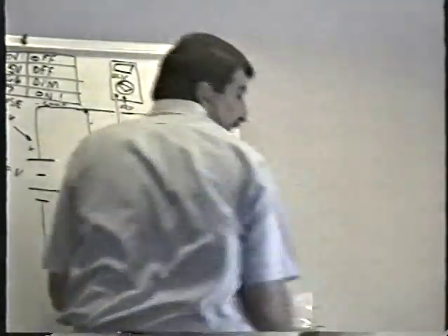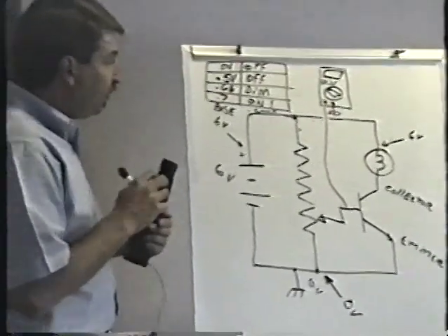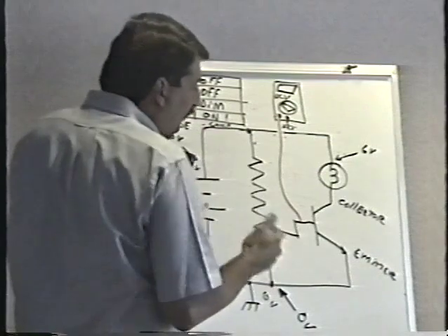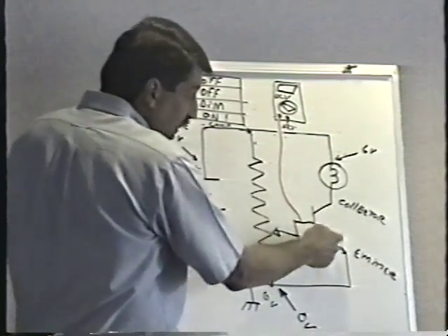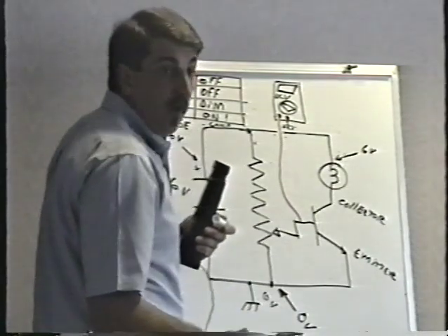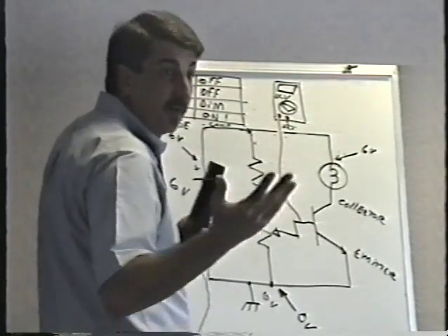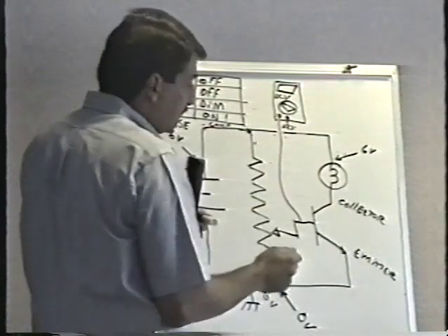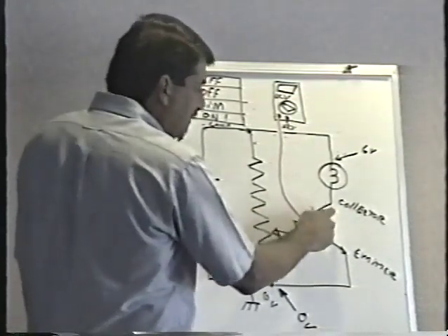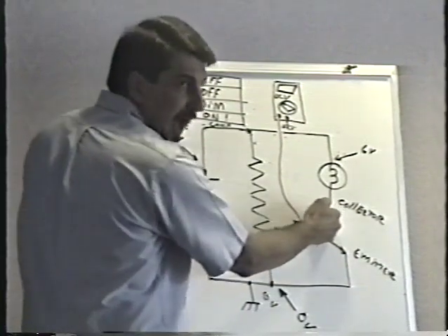I mean, if you look at this, when the transistor's turned off, and there's no connection between collector and emitter, there's really millions and millions of ohms there, right? It's like an infinite resistance. It's a tremendous amount of resistance. As the voltage on the base increases, the resistance between the collector and emitter drops, doesn't it?